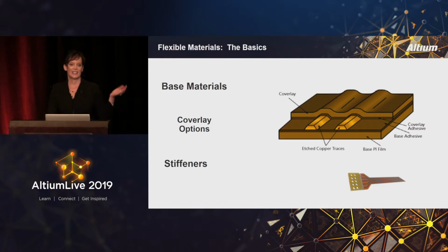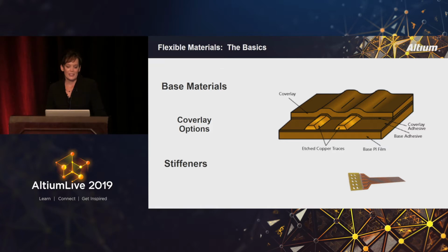In laminates, there's a wide variety of choices. You can have anything from half-ounce copper to 2-ounce copper, half-mil polyimide to 5-mil polyimide, and all different combinations of that. And all of these laminates are going to come in two different types: adhesive-based and adhesive-less. Adhesive-based will typically be an acrylic adhesive or a flame retardant adhesive. Adhesive-less, as the name implies, eliminates that adhesive in the laminate.